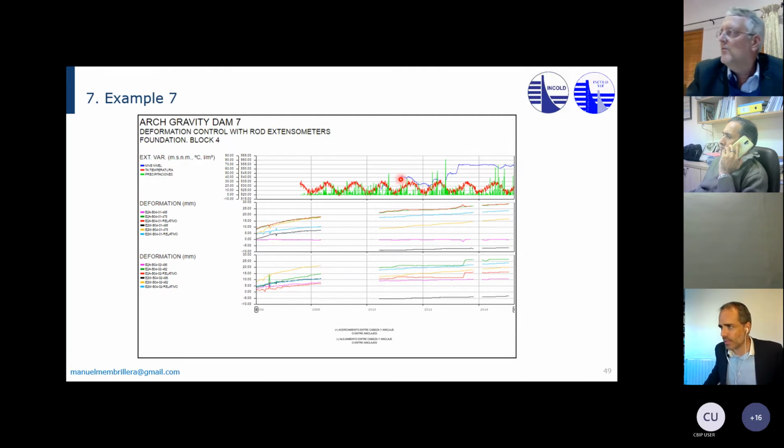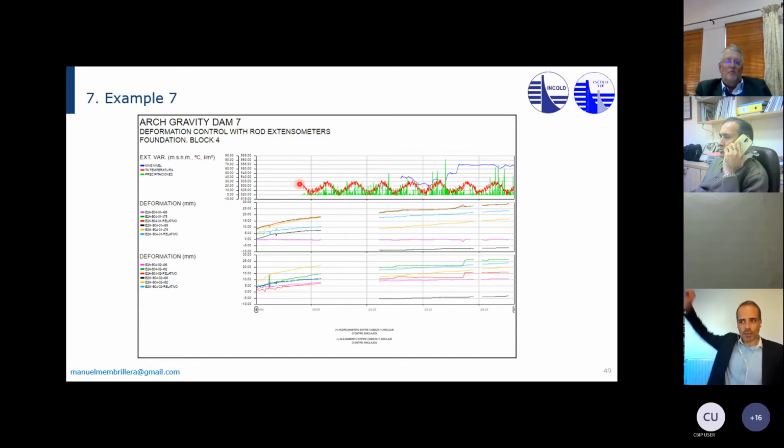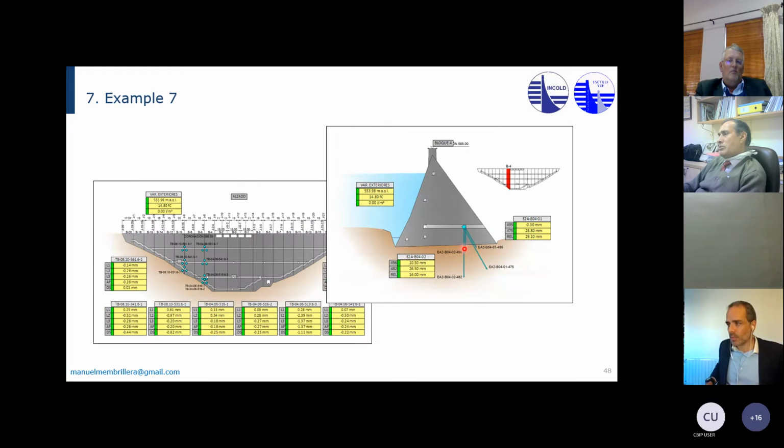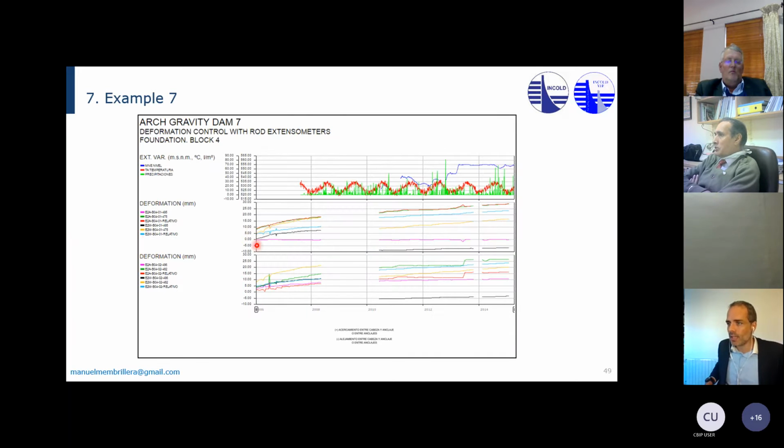This is the first filling of the dam, 2011. But really 2012 was the first filling of the dam. But you can see, so this is during the construction. And if you have a look at the evolution in millimeters of this rod extensometer, you can see how it goes from 0 and it slightly, look at this gap.